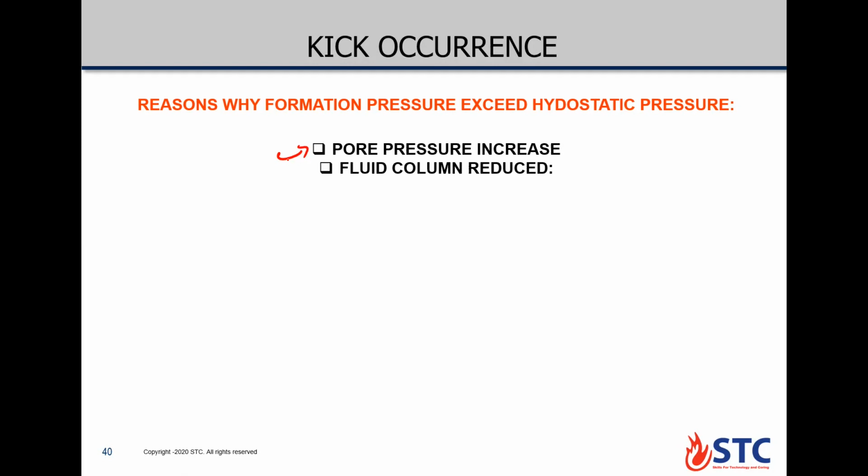When we talk about the reasons for abnormally pressured formations, we have many. First one is under-compacted shale sand. Then we have gas cap rock. Then we have fault formation, surcharged formation, and artesian well, and many more reasons like salt domes and tectonic movements. So for any of these reasons, the formation pressure has a sudden jump to become abnormally pressured. Now formation pressure will be larger than hydrostatic pressure, so it will be an underbalance situation, and we're going to have a kick.